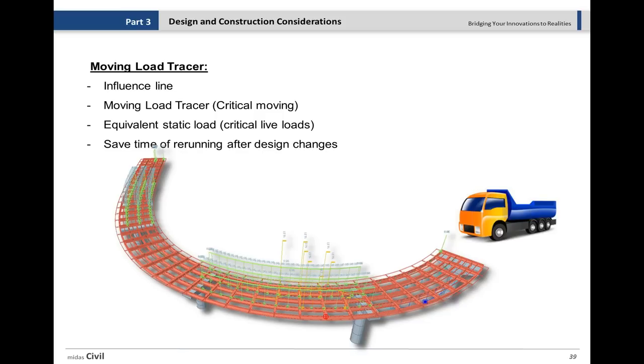All right, how to find the critical forces? It depends on the width of that bridge. It might become more complex. But if you have one or two lanes, it probably is easy to do the hand calculation. But if you have a wider bridge, and you have a couple of vehicles running at the same time, you may not be able to find the critical force for every single element of the arch, and also for the tie. So you need to use software for finding those functions.